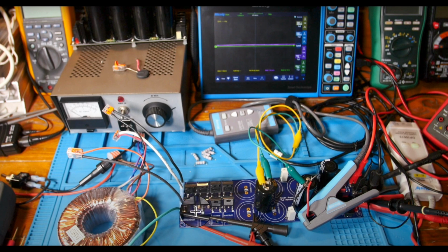So we're going to look at the voltage waveforms, we're going to look at current waveforms, okay? And there's another differential probe off the screen, and some other probes over here on the output voltages, okay? What we really want to pay attention to is the current and the input waveform. And I have this variac, this B&K, that I'm going to use to power it.